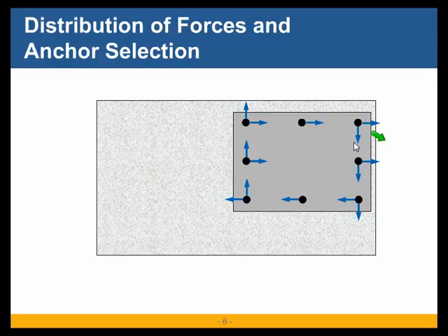a net shear that is acting on these 5 anchors, and then it would also calculate the net shear and its strength on these 3 anchors that are in the opposite direction, and see which one is governing, which one has the lower strength, which one has the more chance of failure. Is it going to fail in this direction, in the positive x direction, under these loads, or is it going to fail under the negative x direction, under these loads?